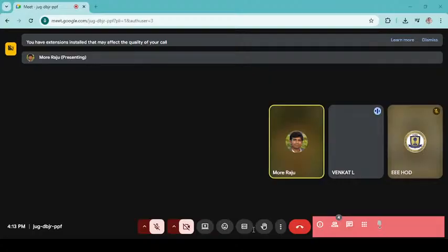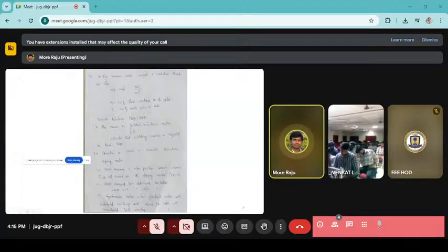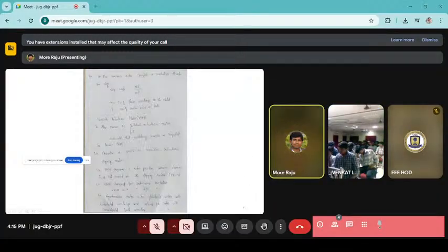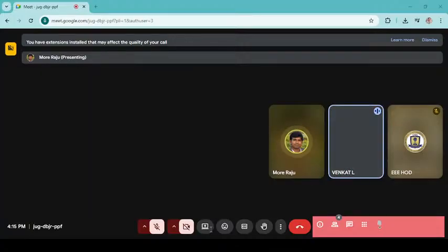So the step angle, how we can measure it, is given as 360 degrees divided by MP. So that is what I have written here. In this manner, the rotor completes a revolution. So 6 steps, because we have a 6/2 stepping machine, where you can see 6 stator salient poles and 2 rotor poles.